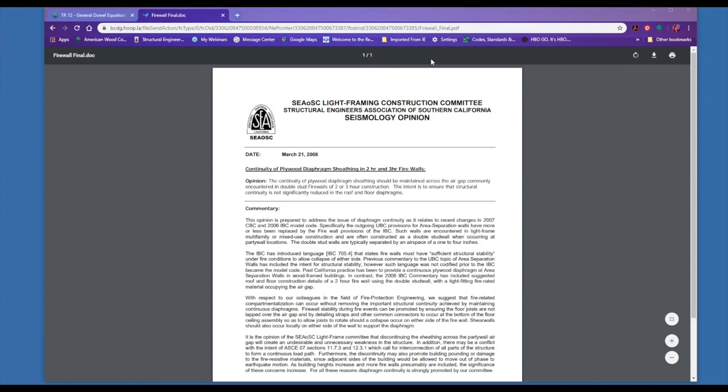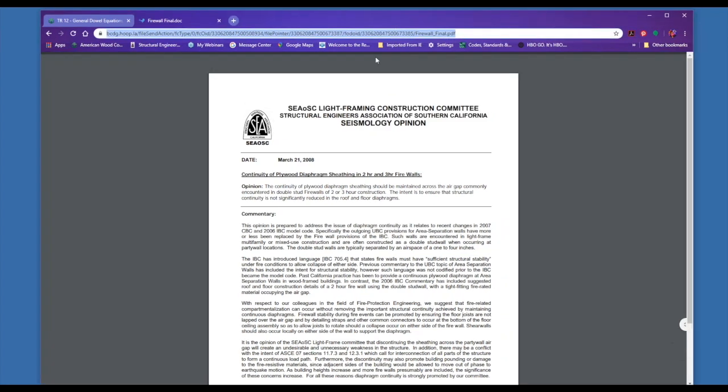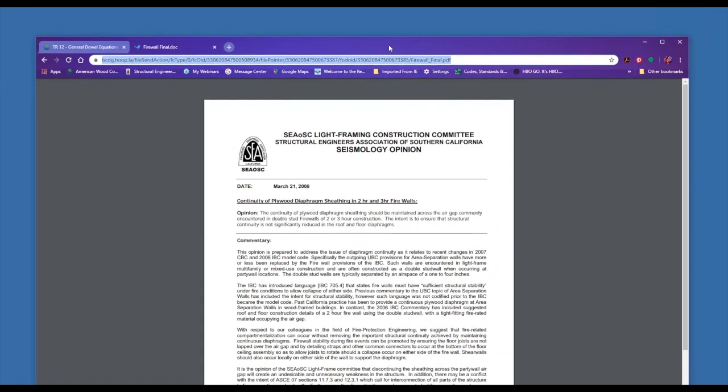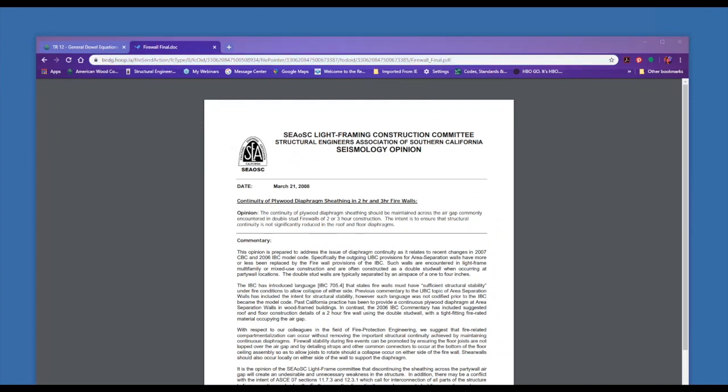Okay, there was a question that came in about ventilation under the balcony, if it's all exposed, and whether or not ventilation is provided. And that section of the code talks about those balconies that are enclosed needing to provide ventilation. If it's all open, it has its own natural ventilation provided. So no additional ventilation would be needed.